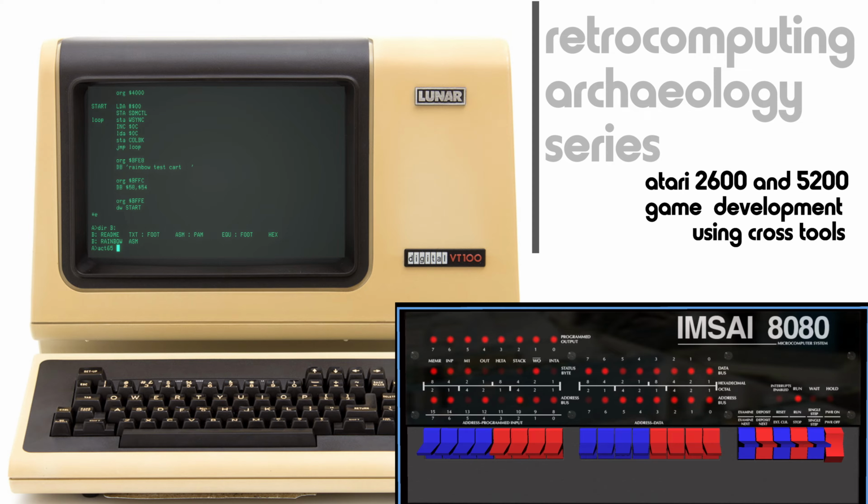Because of where the org statements are, we're starting at 4000, and we have orgs that go up to BFE8 and BFFE. We're writing a word at the end of the statement here. This equates out to exactly a 32,768 byte cartridge. So let's go ahead and ACT65.